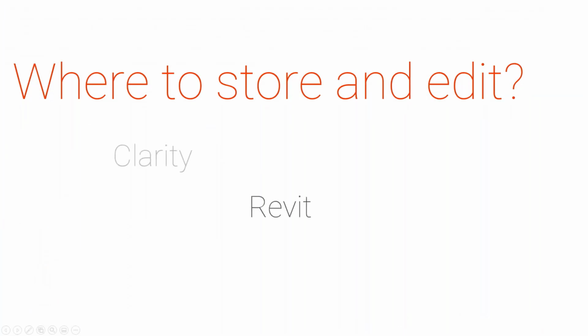So for us, we've tried to figure out, do we edit in Clarity, Revit, or Excel, and it's become a pick-your-own-poison. So we've just made sure that we know how to do each of them and then work with the teams to figure out the best way of doing it for them. The one thing I like about Revit versus all the other methods is I can sort and dynamically change that schedule in ways that I can't in Excel, or not as easily, and I definitely can't in Clarity. I'll sort it all by room name, and then change some of the finishes that just match by room name. I can do some things very quickly that I would do on an individual level in all the other platforms.